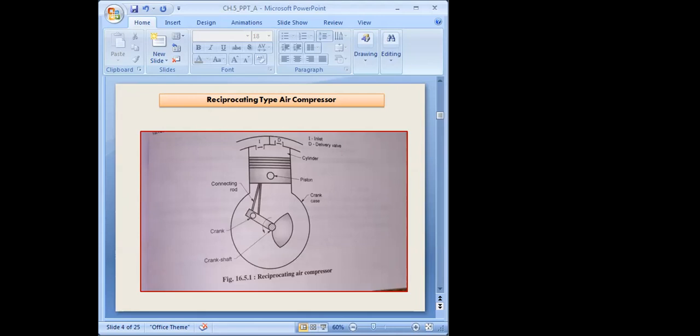Here the air compressor is the energy conversion element. In this pneumatic system, it imparts mechanical energy to the air by compressing it. The main difference between the pump and the compressor is that the fluid delivered by the compressor is air that is compressed, and it is under pressure at the time it is delivered.